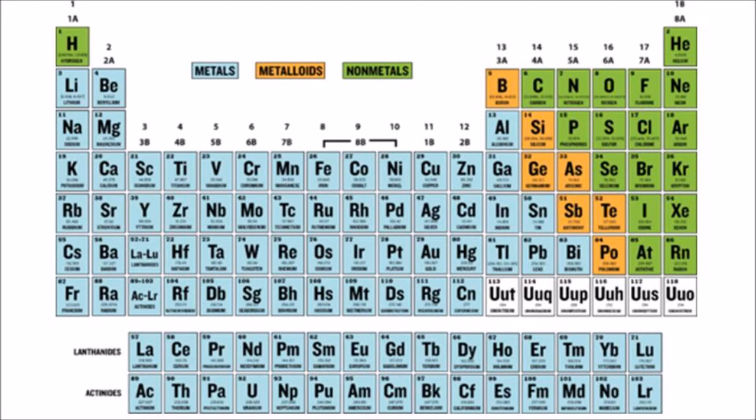The semiconductor dopant atoms are defined by the column of the periodic table in which they fall. The column definition of the semiconductor determines how many valence electrons its atoms have and whether the dopant atoms act as a semiconductor's donor or acceptor. The group 4 semiconductor uses group 5 atoms as donors and group 3 atoms as acceptors. The compound semiconductors use group 6 atoms as donors and group 2 atoms as acceptors.